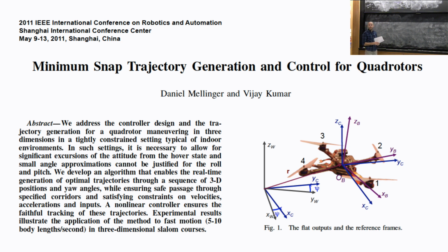In order to make the system controllable at the top, you have to include one more effect, which is the fact that when you spin up your motors and apply a torque, there's rotor inertia, and so there is some coupling that causes yaw when you spin your actuators. If you don't have that, then if you just think of them as pure force sources at the four props, then actually you don't have the ability to control yaw. Okay, so the quadrotor model, to make all this work, requires that rotor inertia in it. Otherwise, it's almost the same as the free body diagram. Okay?